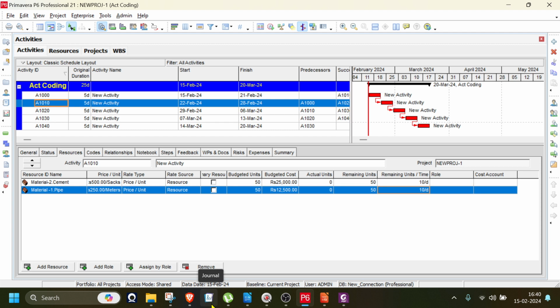So this one is a very small project. There are resources there. You have to add the resources: design engineer, project engineer, supervisor, officer, all those resources. Then you assign them on the project one by one. It is mentioned already there on the table. There are no materials here, only manpower. Oh, there is material: sand and cement. Cement you already created, so the unit is already there. For sand, they are saying the sand is in cubic feet. So you have to create the unit cubic feet. Then assign what is said.